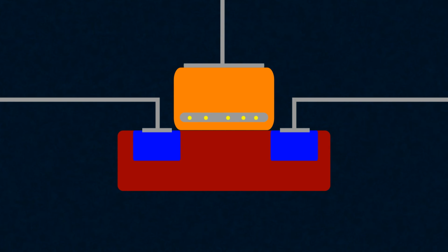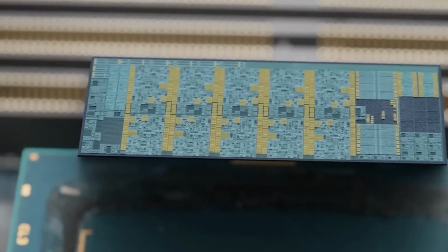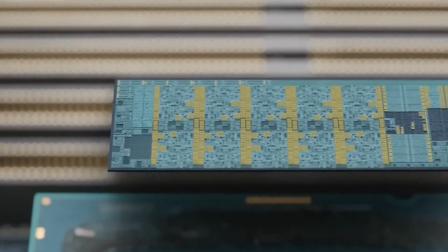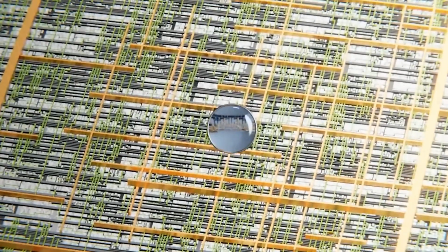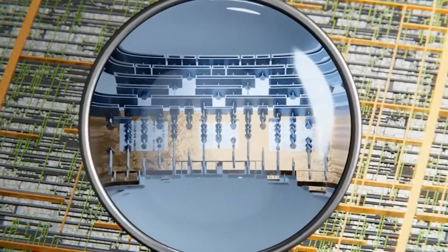More precisely, over time, electrons will leave the floating gate thanks to the same tunnel effect. However, without an external voltage, they will do so very slowly. The floating gate can retain charge, and the cell, the data written in it, for years. Furthermore, to store one memory bit, we only need one transistor, as opposed to 6 in the case of SRAM, making flash memory cheaper and providing it with a higher data storage density.